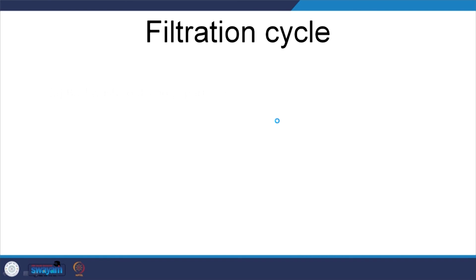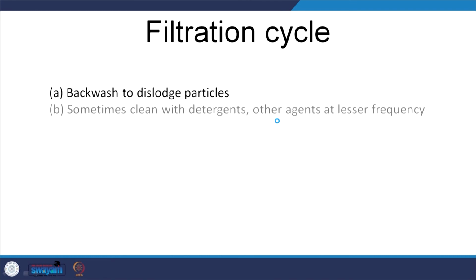So, filtration cycle: you will have to have backwash to dislodge the particles from time to time, similar to your depth filtration, and sometimes you will add chemical agents, depending upon the type of scaling or such that is occurring on your membrane.